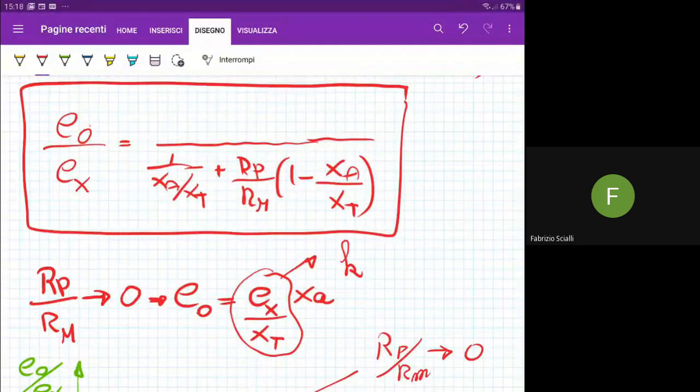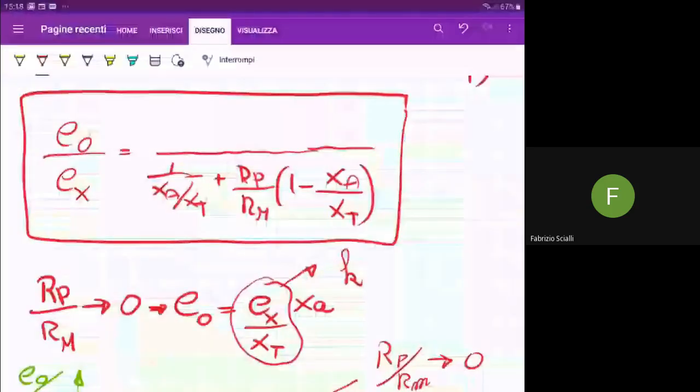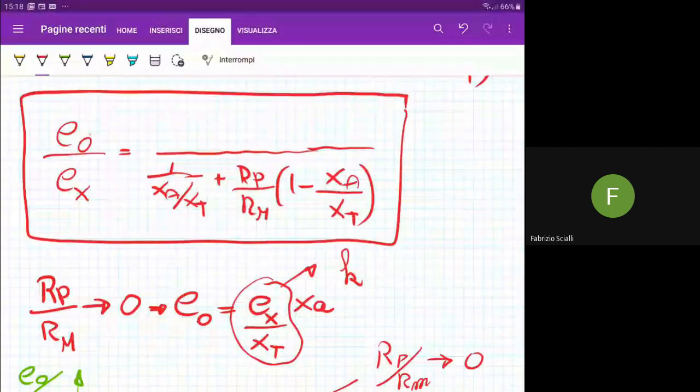That is, there is no delay between the measurement and the actual value of your unknown quantity, the displacement. There is no first order or second order time domain differential equation governing the operation of this working principle. It is just zero order, no delay. What I'm measuring is just what I have, if all the measuring devices, that is the potentiometer and the measuring system, are described in terms of resistance as I did. So no special issues about that.